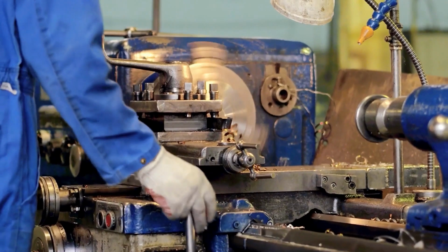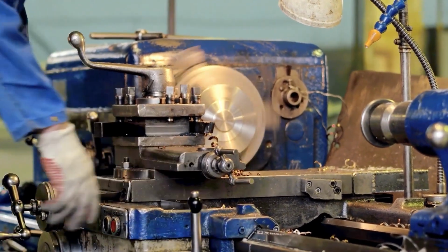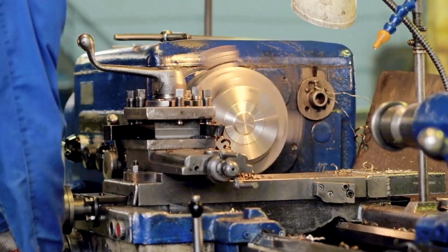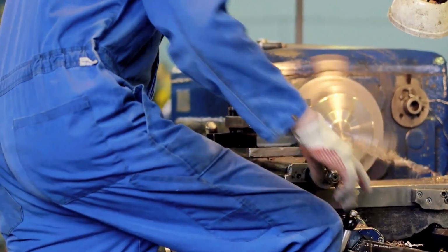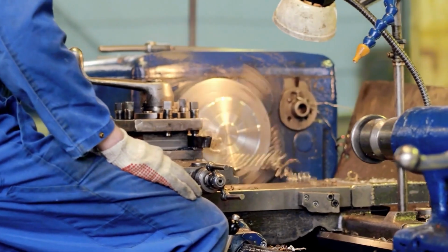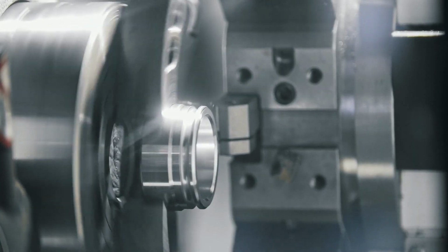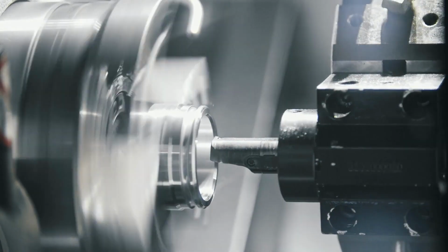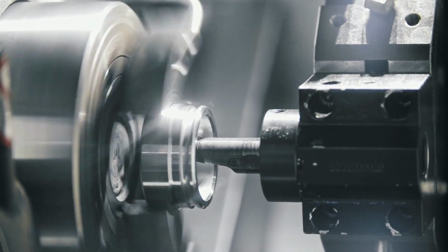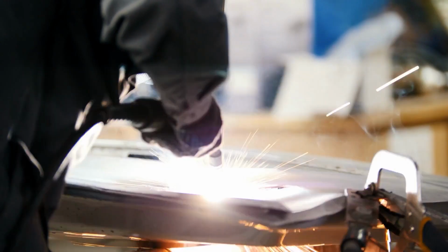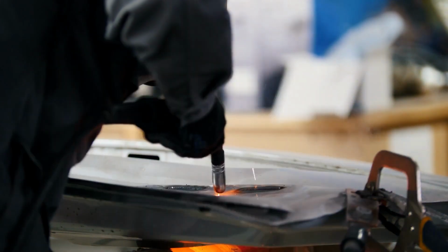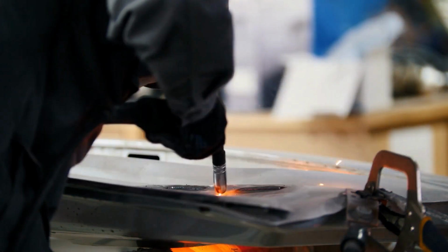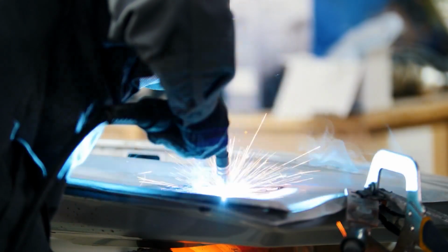Ideally, these machines and equipment will already be equipped with proper guards and safeties. However, all guards require regular maintenance and tightening to be kept in safe operating conditions, and far too often employees habitually defeat machine guards because they believe it makes work easier or more efficient. Well, there is nothing efficient about having body parts amputated or crushed due to improperly guarded equipment. Machine and tool guards should be replaced when they are no longer safe to use. You can determine this through daily visual inspections and implementation of a preventative maintenance and replacement schedule.